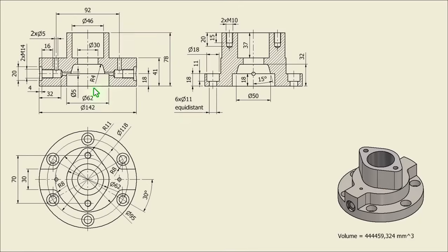Okay. Next is this combination of holes with dimensions metric 14 is this, counterbore of 20 on 4 millimeters. The total depth of this threaded hole is 32, as you can see. This is symmetrical, and there is another hole, a small one, this one,